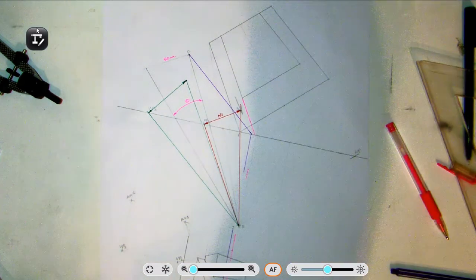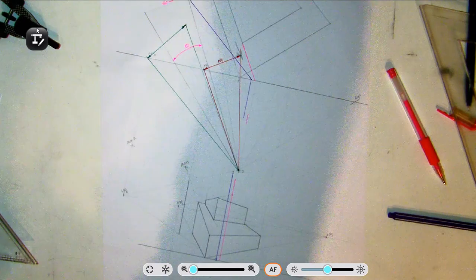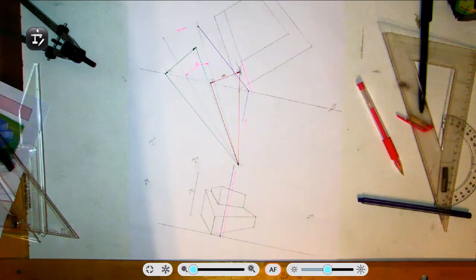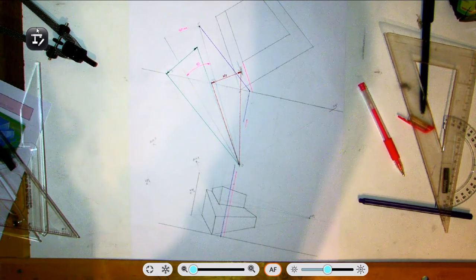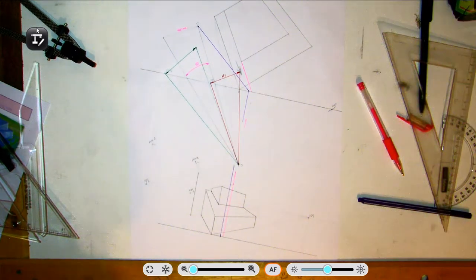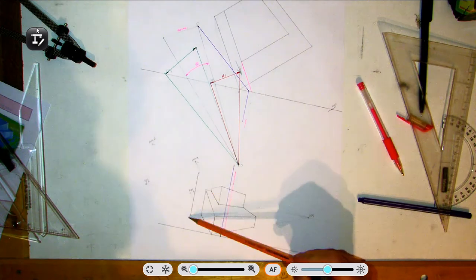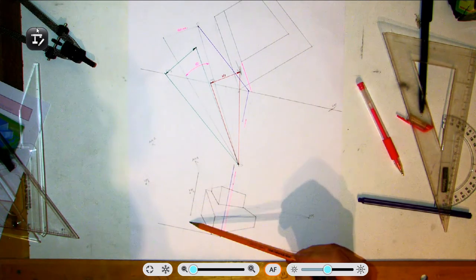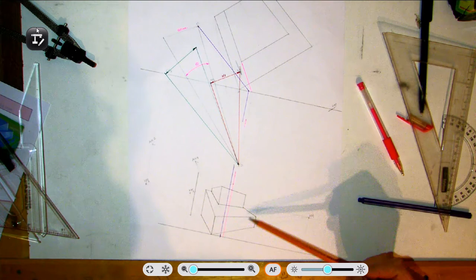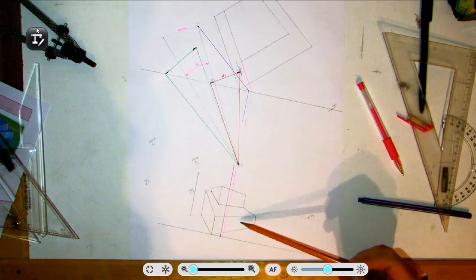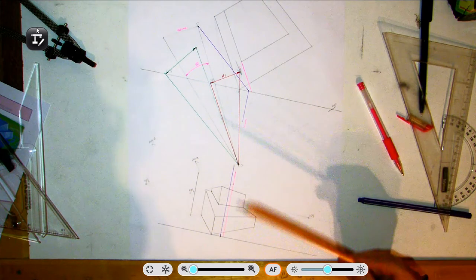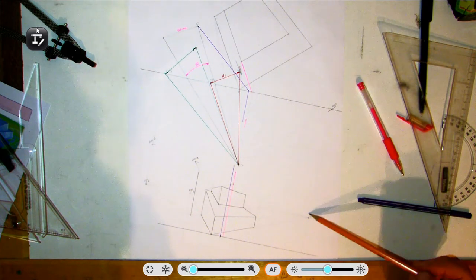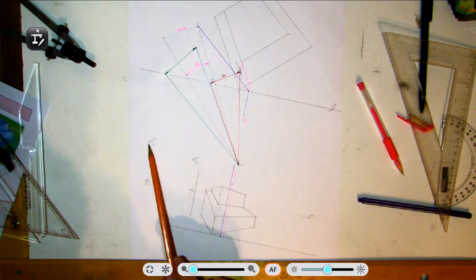So looking at it as a whole, that's the whole 2018 question completed. A few new things that haven't appeared before. Unusual that you have a chimney out, or a separate part of a drawing out away from it. Now it is a really simple structure when you look at it. There are only 2 blocks on it. There are no curves, but in order to be able to draw it, we needed to use 3 vanishing points and then 2 auxiliary vanishing points.